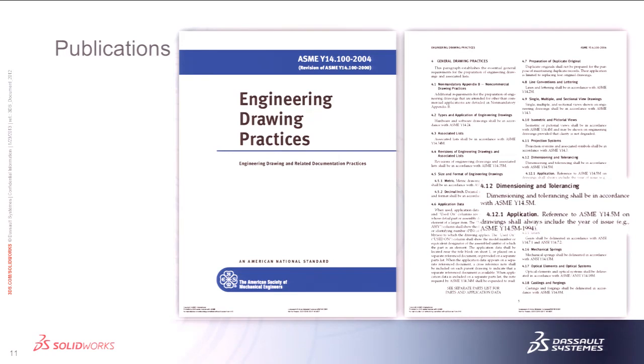The other part that we need to hit on is you don't have to put the date with the Y14.100. A lot of people argue back and forth. The way that works is if you don't put the date on most standards, they're going to take the current revision as the standard they're going to look at and compare it to. So basically you're saying anytime the standard's revised, look at the new standard.